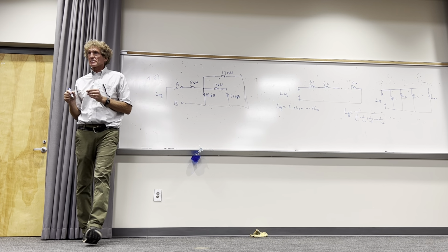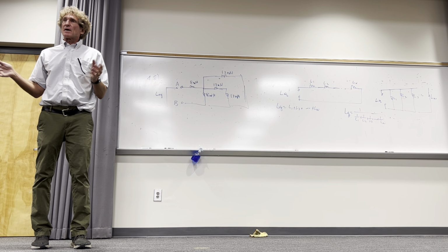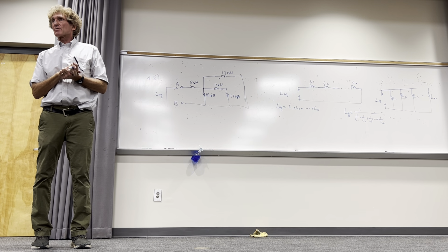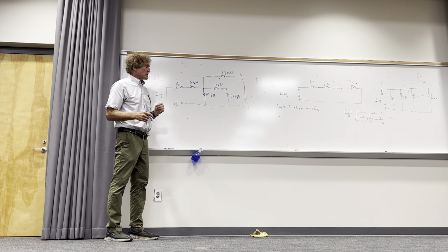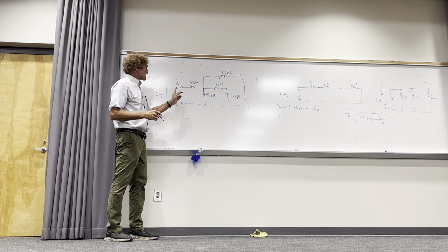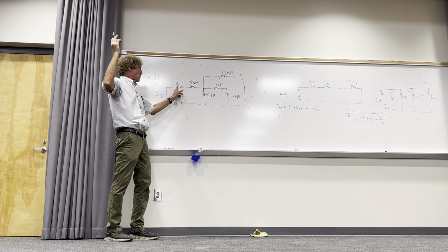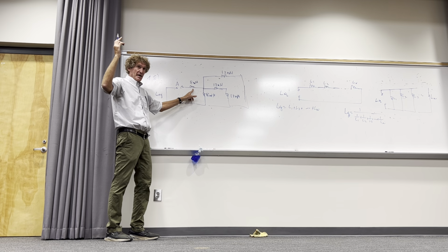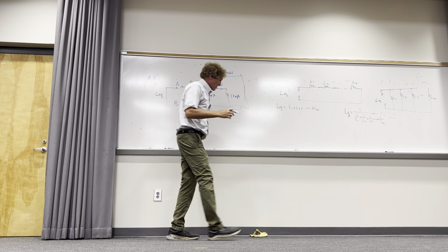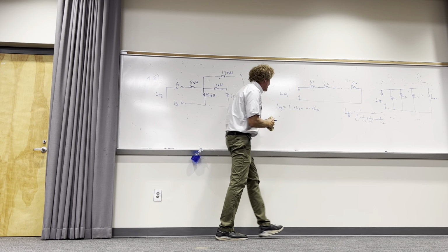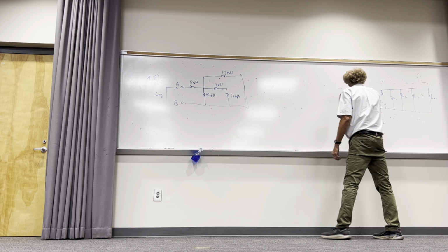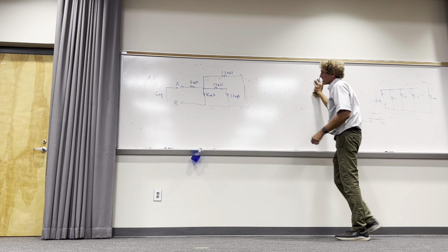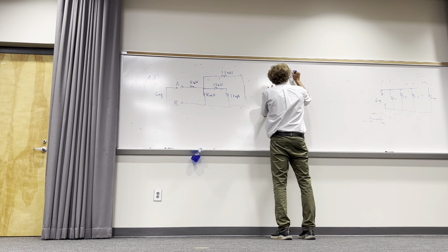Can everybody see this okay, class? Now, I always tell you to simplify the circuit. First, take a look at it. Don't just knee-jerk react. When you look at this thing, we could use the color method if you want. But you see this is in series, right? Do you agree with that, class? Just show of hands if you do. The only way current gets from A anywhere is going through that 8 millihenries. Do you agree with that? So for the redraw, I'm going to put it over there. That's going to be 8 millihenries. I want to put it right here so you can see it. Here's terminal A.